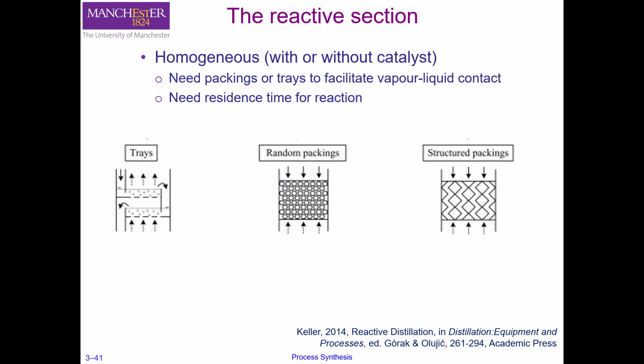These packings allow the liquid to form thin films, and these thin films can have excellent contact with the vapor phase. Okay. The most important thing is that the design of the packing should be such that it allows enough residence time for the reaction to take place.